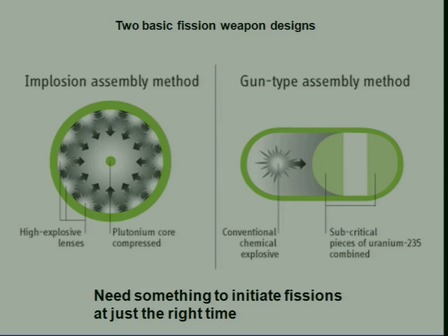Very often, what's in the bombs is metallic uranium and/or plutonium with other things added in for various reasons. The question is, what happens to that metal as a function of time because of all the alpha decays which are happening in it? First of all, you get dislocations in the material from the alphas and the daughters recoiling. Second of all, the alphas stop inside the material, and what you generate is helium gas. And so there have been a lot of studies over the years as to what happens to this material as it so-called ages. The conclusions I've read, which again are not classified, is that basically nothing happens. Okay, that's not going to be a problem.